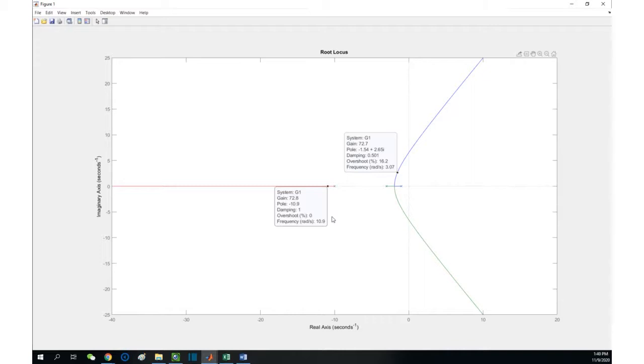Yes, you can say that, but John is right. Everybody, don't take me wrong. If you're looking for all of the closed loop poles, yes, you have 3 poles. This number is fixed. So 2 dominant poles here and here, and the third pole does exist. You look along the third branch for the same gain, 72.3, then you locate that third pole. However, in this problem and also in our future design project, we are focusing on the 2 dominant poles. The third pole is just used to verify that this approximation makes sense.